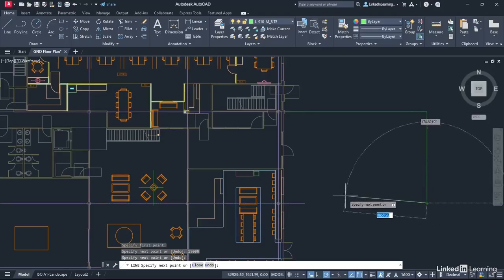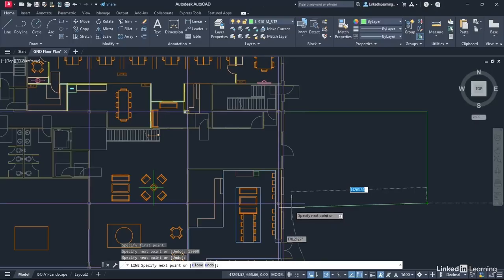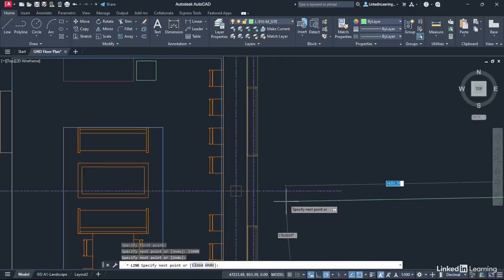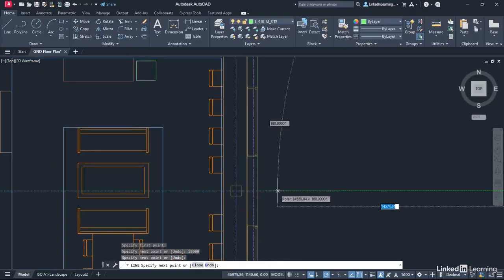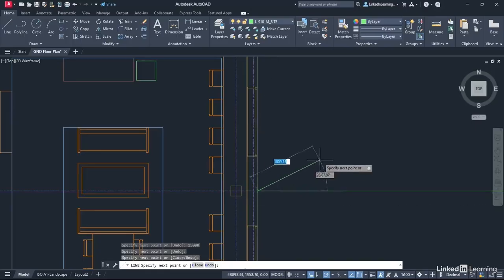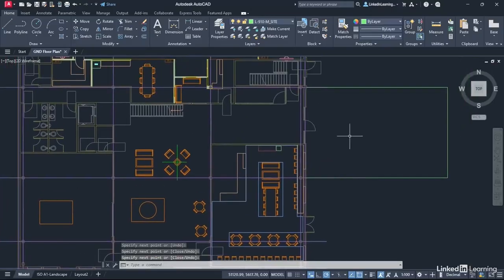And then we're going to come along here horizontally. We'll zoom in. And when you get to the edge of the wall, see the grid line there, just follow that. You'll see an intersection there. Left click again, enter to finish. And when you zoom out and pan a bit, you'll see you've got a nice area there ready for landscaping that you've marked out with those 3 lines.